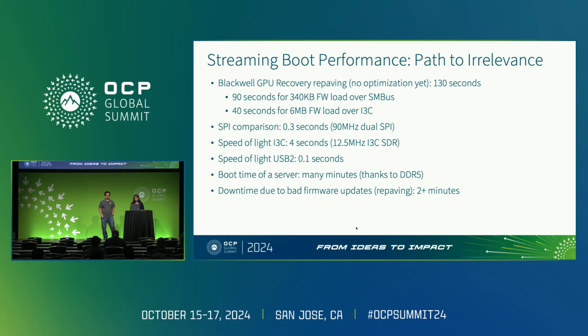Great question. I think those questions are really dependent on your SoC or device architecture today. So if we take Caliptra as a nominal example, Caliptra only executes entirely out of SRAM today. And what it does to mitigate data corruption issues is it implements ECC logic on the SRAM. But because it's executing entirely out of the SRAM, streaming boot versus flash boot doesn't make any difference. It's just a matter of loading that SRAM with bytes. You have the SPI interface or these interfaces we presented today to do that. But once that loading is done, it's never going to touch that I/O interface again.